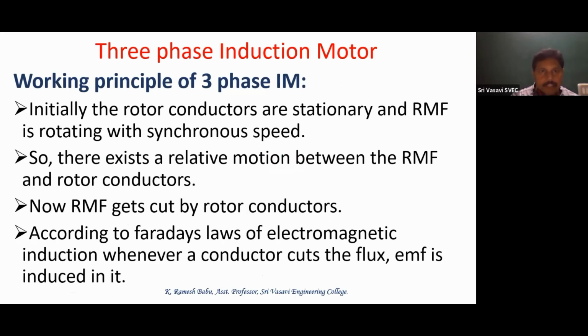Initially the rotor conductor is stationary and the rotating magnetic field is rotating with synchronous speed. So there exists a relative motion between the rotating magnetic field and the rotor conductors. For the motoring action in a three-phase induction motor, this relative motion is very, very essential.